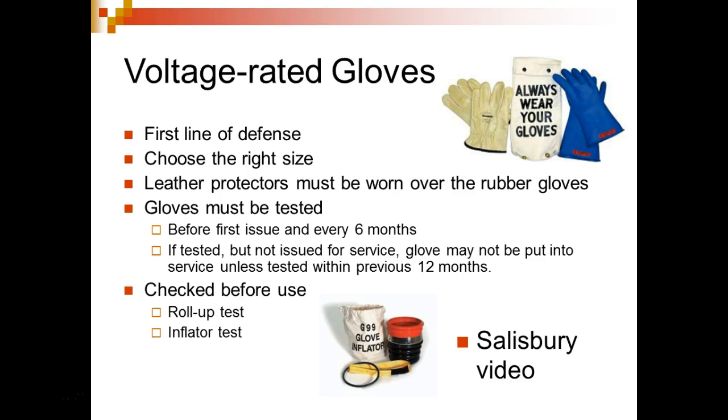But a rule of thumb, they'll put a code on the nameplate, and I'll probably try to give that to you. It's required now, and it tells you how much over the full load current that motor should draw when you try to start it. Well, the problem is when it stalls, it's sitting there drawing what? Starting current. Well, see, there's something going on there because that motor should have been protected against that.